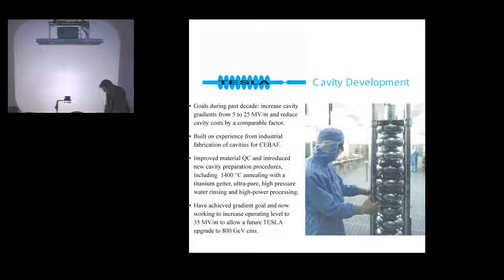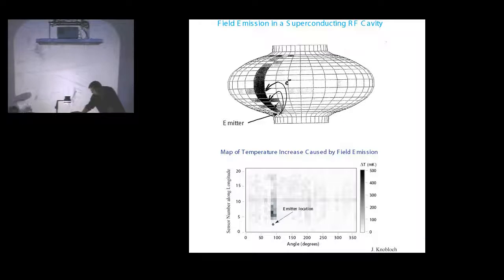So for these cavities, one of the challenges they face is field emission. It's not so much breakdown, where you get this cataclysmic event with a big current pulse, but you get fairly small current pulses due to, for instance, particulate matter or residue on the cavity. And because it's such a high Q system, it doesn't take much current to load down the RF in the structures. That's one of the disadvantages of having a high Q system.